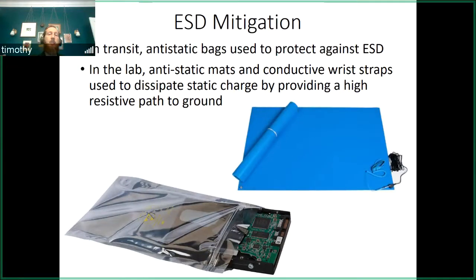Here's the anti-static mat that I'm talking about. You want to have one of these. It has these little plugs on the end of it. These plugs are what you connect to a ground source. So if you get one of these mats, you lay it out on your table at home, and you say, now I'm protected from ESD.